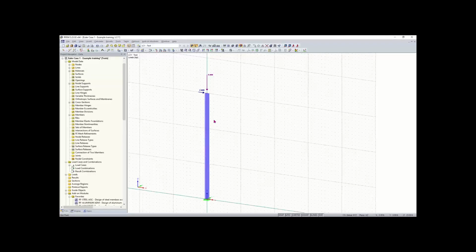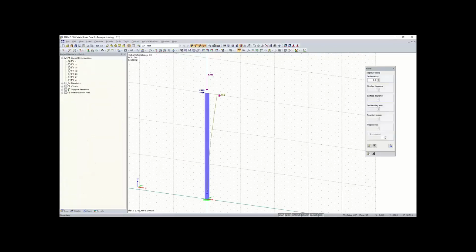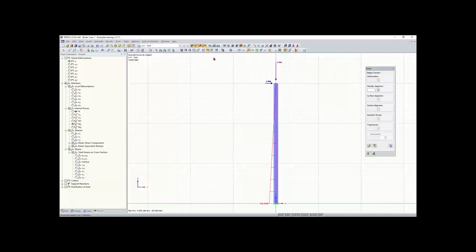And so yeah, now what I want to show you is something important. So this is very important for calculations of structures within RFEM. What I can do is click on Calculate All, and I can run the calculation for this column. And now you'll see that my deformation is shown here, my resultant deformation. I can also go here to member and again show my internal forces. I can show my moment about the local y-axis here. I can get an elevation view of that.